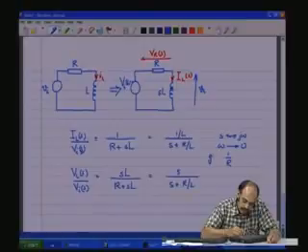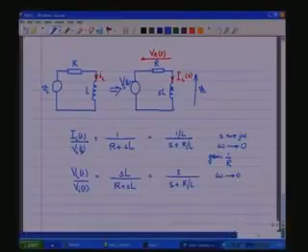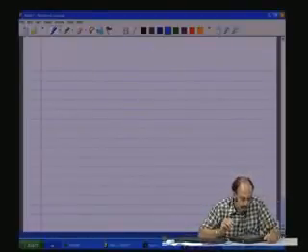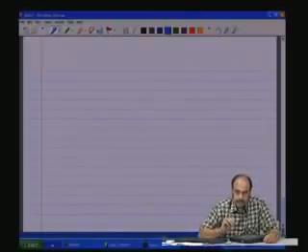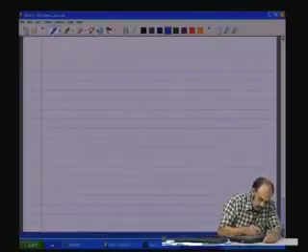So, this is the gain, and in this case, as omega starts tending towards 0, this will also tend towards 0, and then you will see that the gain tends towards 0. So, that is basically the idea that you will have to get from this pole 0 analysis, the transfer function analysis. Let us do one more circuit, which is the RLC circuit, which combines both together.